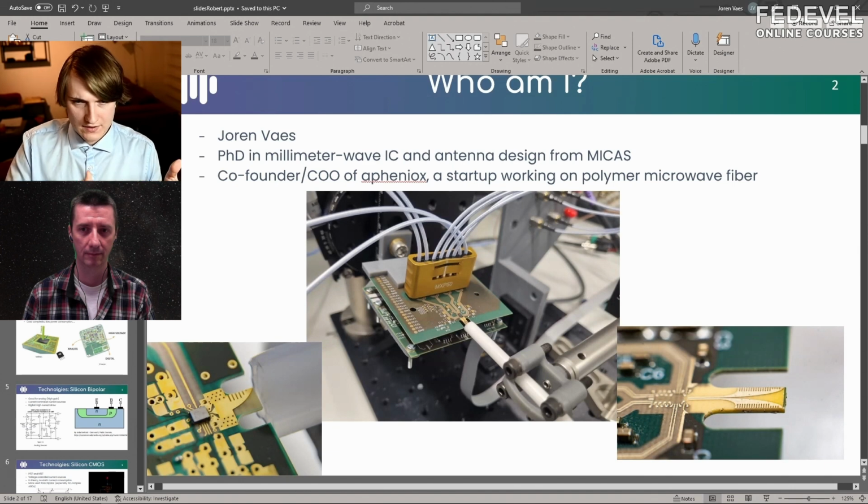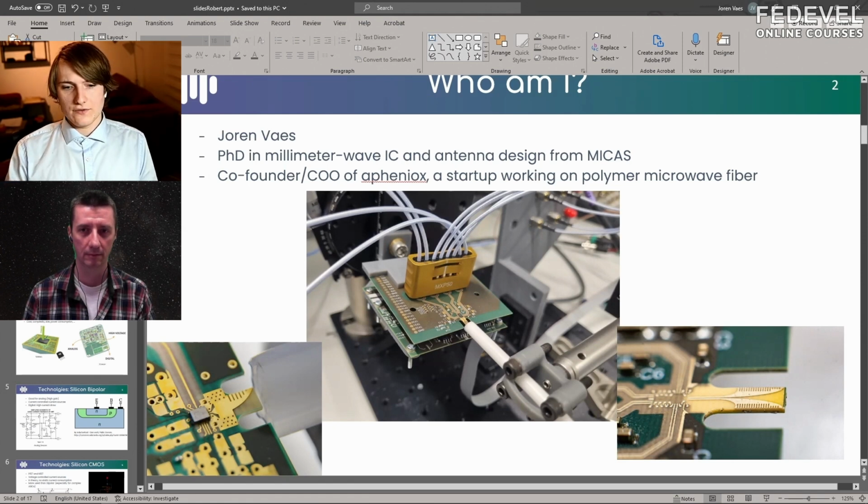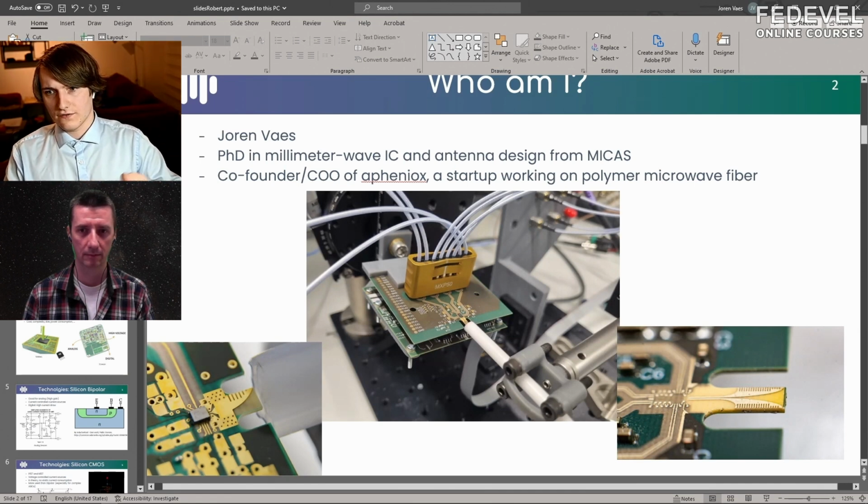But yeah, this is something that they also design too, because for us, for example, at millimeter wave frequencies, this is a big problem in high speed IOs because you add a lot of parasitic capacitance. And so one of the things we have to do is add big structures with inductors to compensate for the capacitors to get a flat response, and to tune out our ESD diodes.